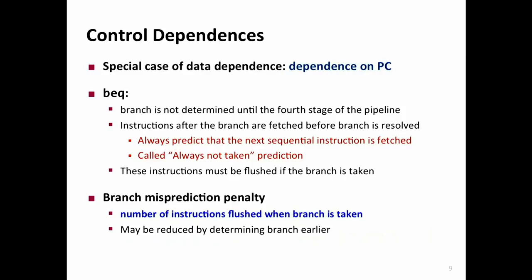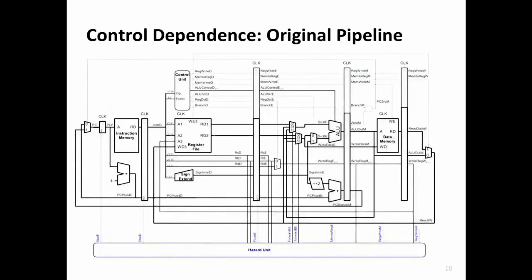Okay, 30% we'll do with 30% for now. But we want really 99%. We actually want 100%, right? Okay, so basically, you can reduce the effect of branches by doing better prediction, or you can reduce the effect of branches by reducing the branch misprediction penalty, right? So if you mispredicted, okay, maybe it's better to reduce the penalty that you have. Instead of having 20 cycles, you make it 10 cycles. Well, instead of having 4 cycles here, why don't we make it a little bit lower?